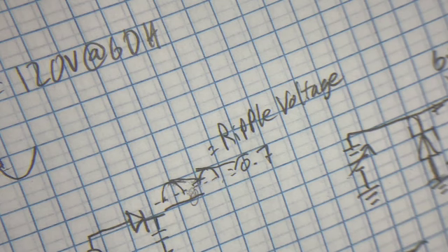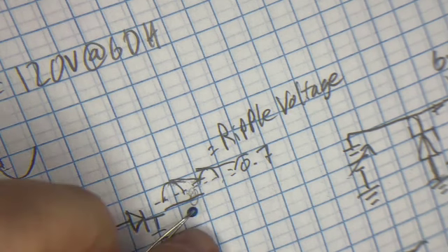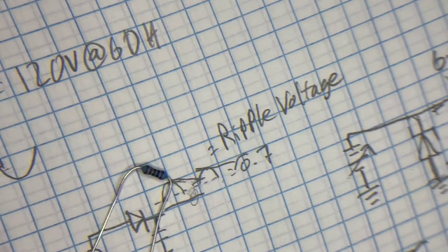Now, what he didn't seem to understand is that the power is actually the voltage across the impedance times the current through the impedance. And when you're looking at something like an amplifier feeding into a speaker, a speaker's a pretty low impedance in general, and the amplifier has an impedance that's designed to match that.